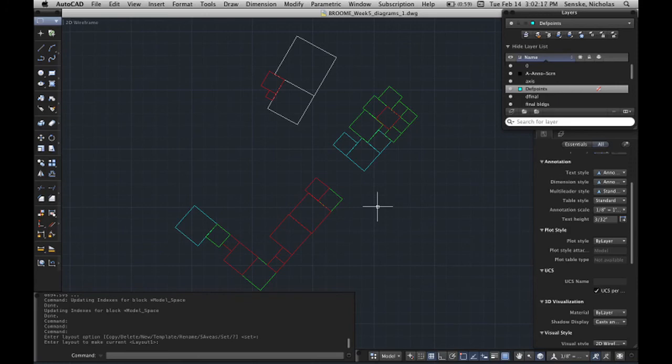36-inch bond color. You'll notice, guys, that there's a difference between the color and the black and white printer, even with the same weights and things. The color and that nice paper will actually give you finer line weights and a crisper drawing than the regular black and white printer. You can use the black and white. It's very economical. You can get a lot out of it. But it's two different things, the color printer and the black and white printer. You do need two different settings on your Illustrator file, okay?